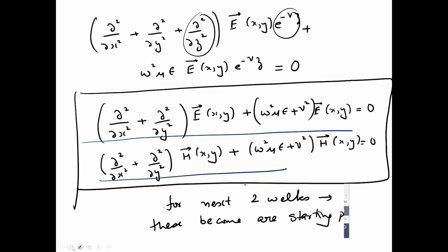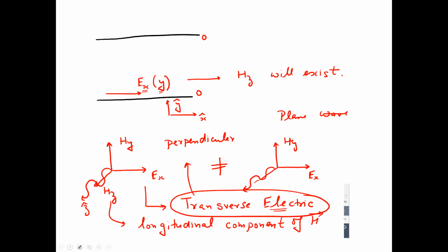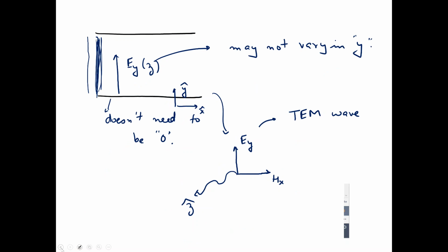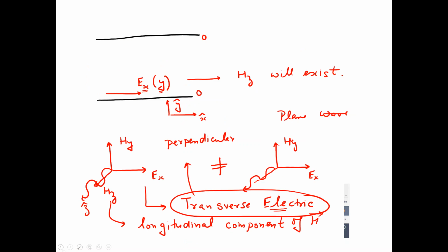So we're going to say, all right, I know that the solution for the TE wave is going to have an EX component, an HY component, and an HZ component. Maybe I can start with my EX component, because that is parallel to the boundary, and it has to go to 0 there. What would the solution look like inside? What happens to that solution? And we're going to find some very interesting results.